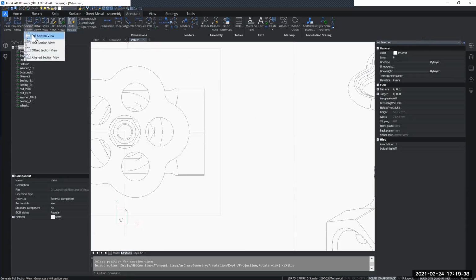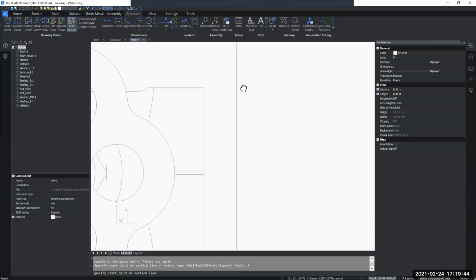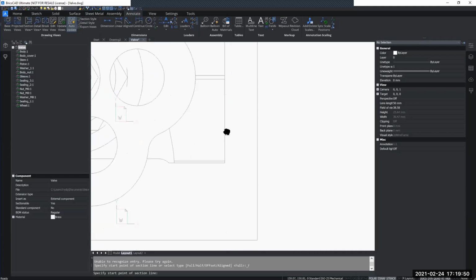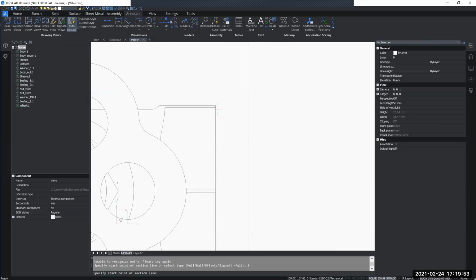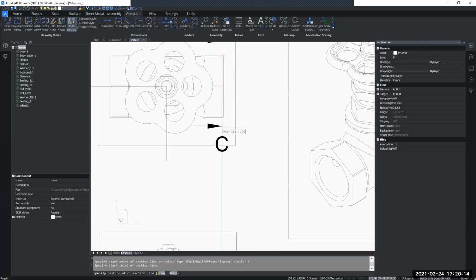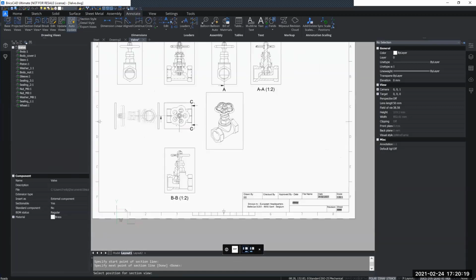So then I can go ahead and create another full section view, select the drawing view. Now I just want to capture the silhouette of this face here, basically. So I will just start my section line a little bit in past the face of it. Specifically, it doesn't matter as long as it doesn't touch much else or go past this shape, just like a few millimeters past. I will start my line, draw it downwards the same way as before. And I will move it to the side.